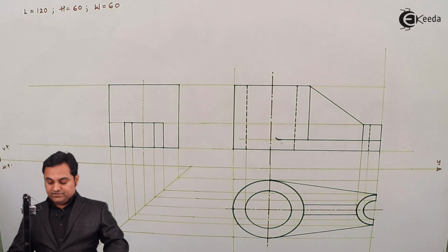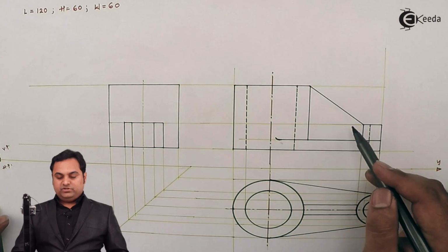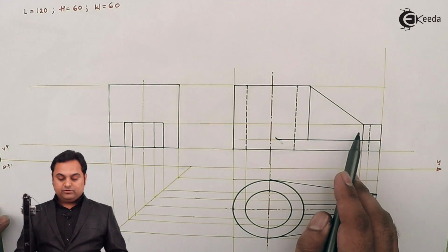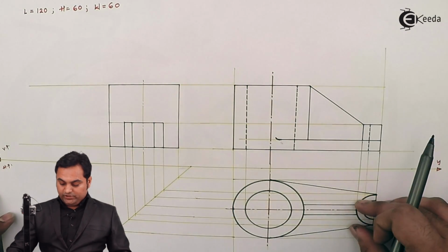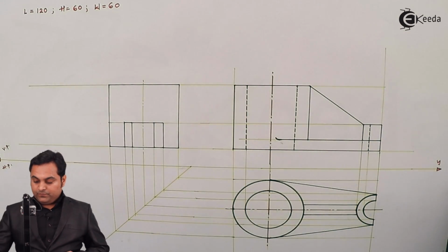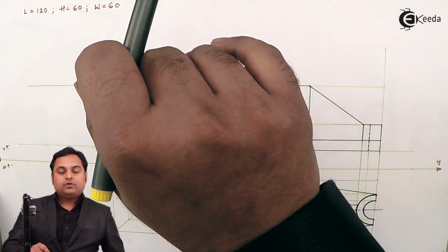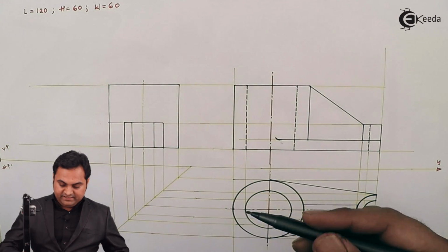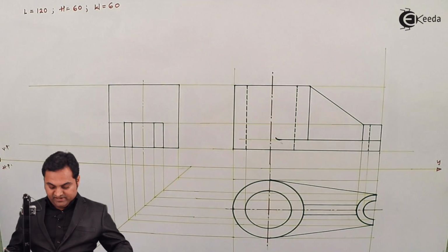Next, after making this cylinder dark, there is a rib which is connecting the cylinder with the semicircular part. So the height of the rib we already have. Now width will be projected from the top view. Either we can project the rib from the top view, or since it has a width of 10, we can measure 5 mm on both sides. That will also be fine.